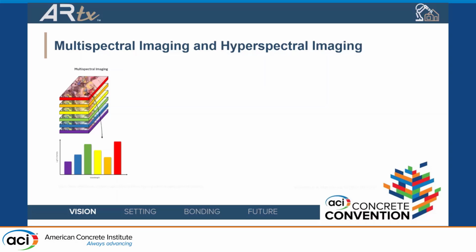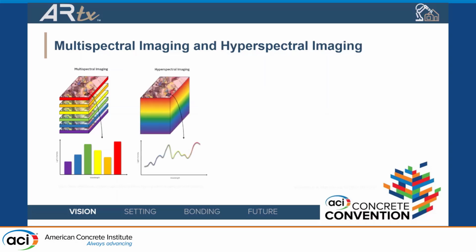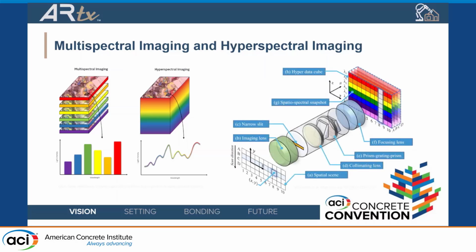Hyperspectral images use a prism or a slit to spread the spectrum, and they scan one line at a time. So in your 2D array, one dimension represents your horizontal pixels in the line, and the vertical dimension represents all these different spectra that the line got spread apart into after it was pushed through the slit. If we scan line after line after line, we can generate a bunch of pictures at very small bandwidth bins to look at how an image is reacting or reflecting in different band passes.